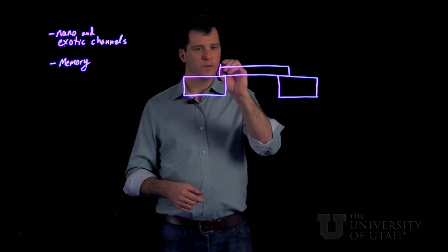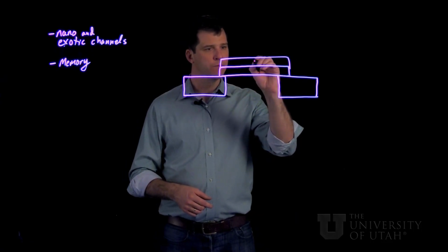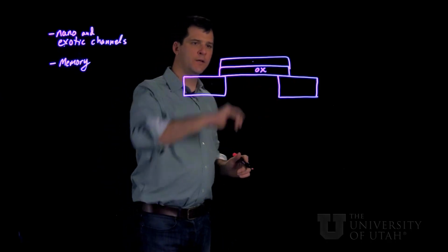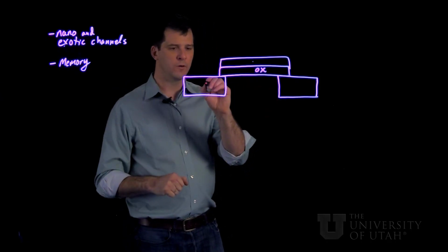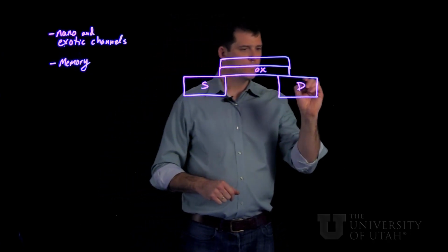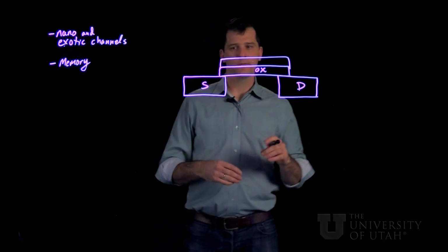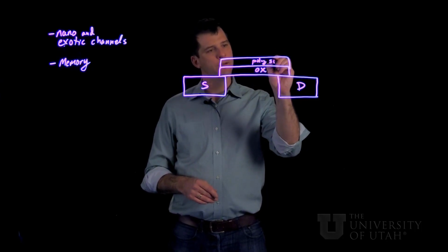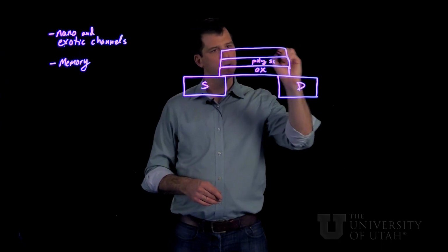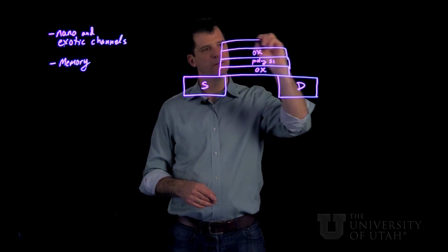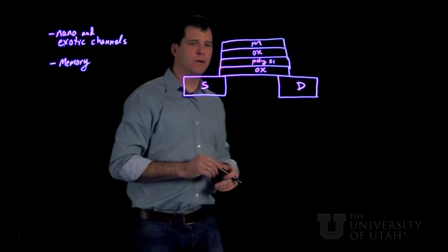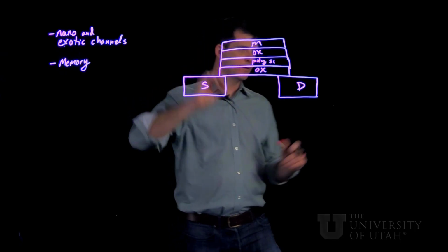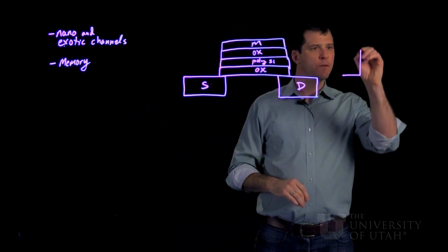So let's go back to our basic MOSFET structure. And now instead of making the gate out of a simple metal, we're going to form a more complicated structure. So we could put some other polysilicon there, and then another layer of oxide, and then a metal. Now, what does this allow us to do? Let's look at the band structure of this region here. Essentially, just looking at the conduction band,